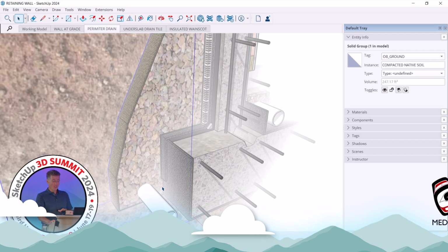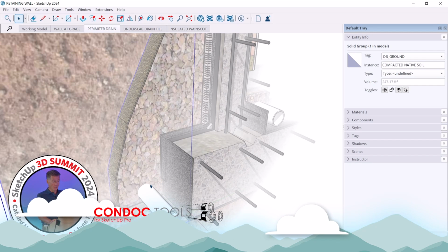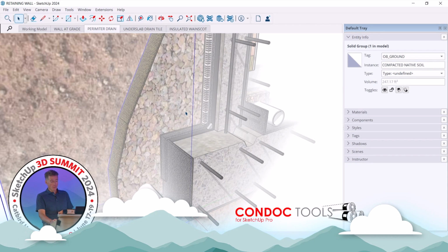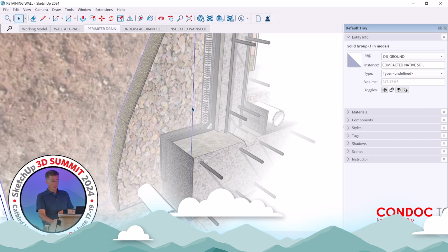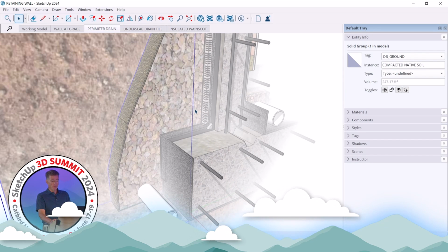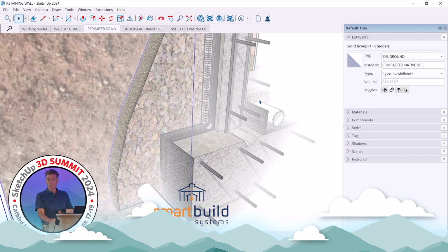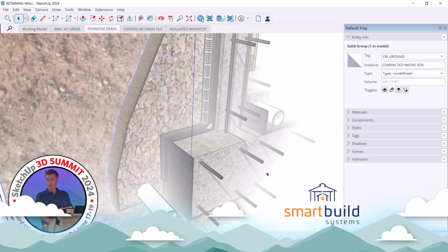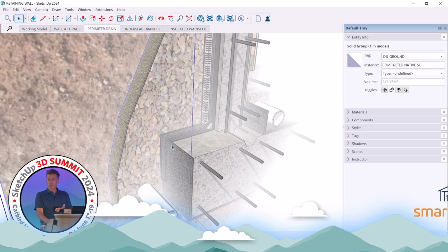So we were having this discussion earlier, because a lot of contractors and a lot of architects are used to that drain being right here. So if you have a slab condition like this, that works, but you have to ensure that the depth of that footing is pushed down far enough that that drain is set at least a couple inches below the slab. Because if you don't, any water that comes up from groundwater, takes the path of least resistance, and is going to go inside before it hits the drain. And I've seen it happen.